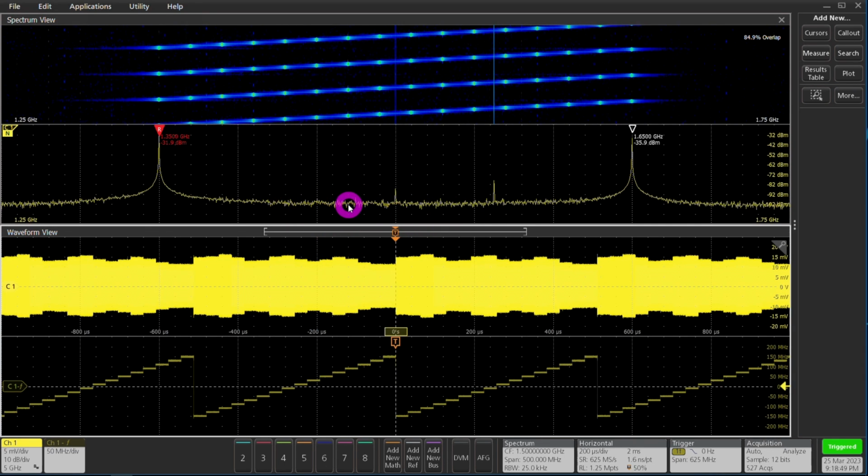Now here we're looking at a much wider bandwidth. We're looking at a 500 megahertz analysis bandwidth. This can go up to 2 gigahertz, so this is not a problem at all for it. And we see the complete ramp now. And you can see that the steps go all the way up and then jump back down, all the way up, and there is a plus and minus 300 megahertz of sweep there, which is far above the 165 that SM435C could show us. So this shows again that an external digitizer with its own sophisticated DSP can accompany this instrument and do a whole bunch more.